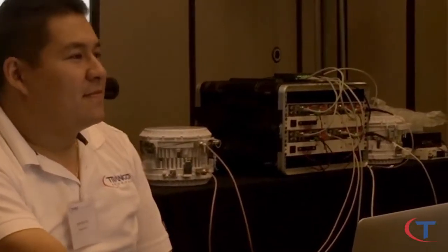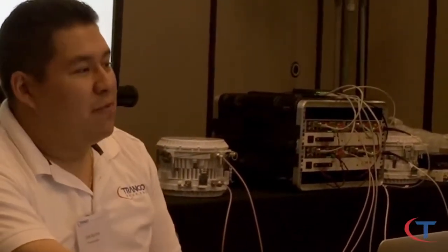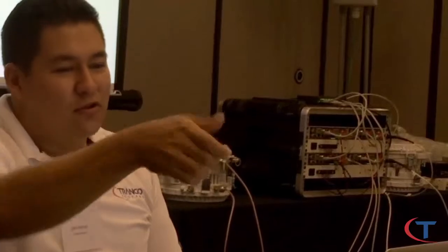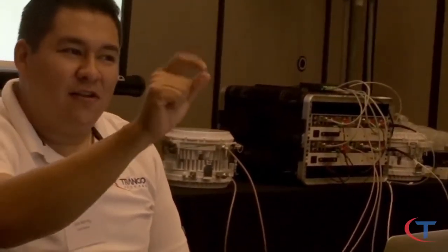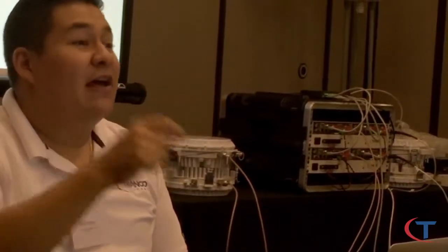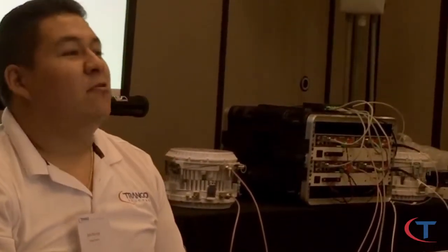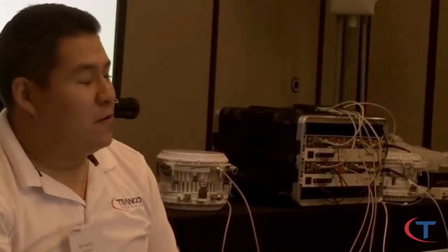Rule of thumb, you cannot unplug the IF cable if the audio power is on. If by any mistake you unscrew the IF connector and wiggle it a little bit and the center pin touches the conductor, it's going to blow the fuse on the end connector. At that point, it's going to come back to me, I'll RMA it and send it back to you. It's not field changeable.